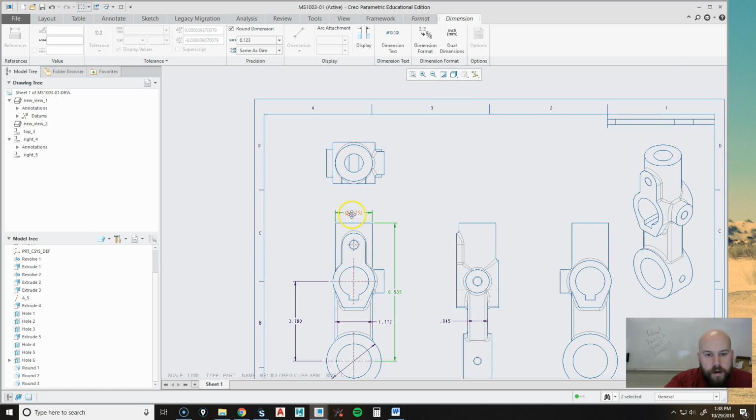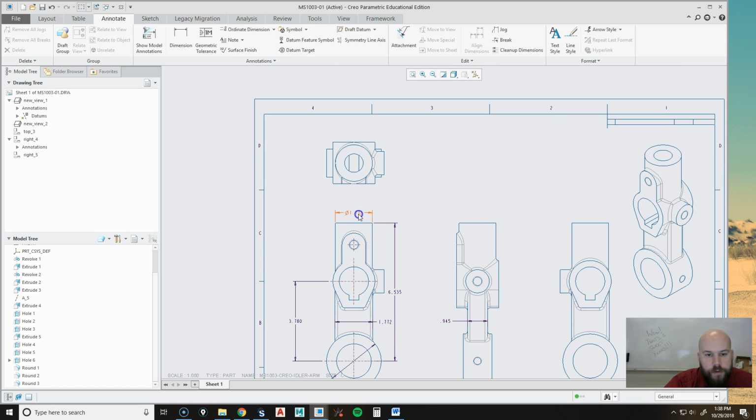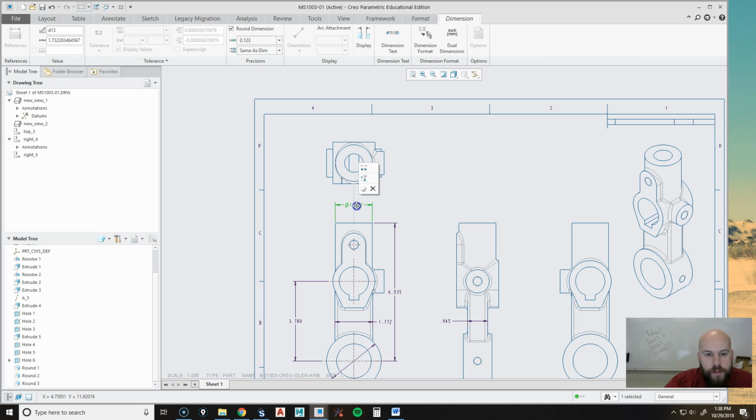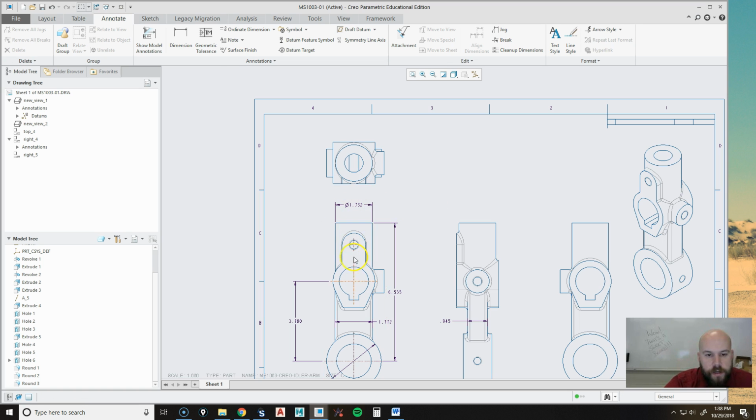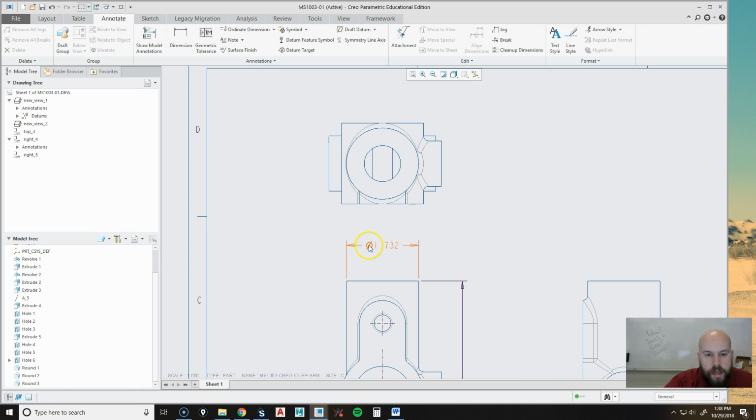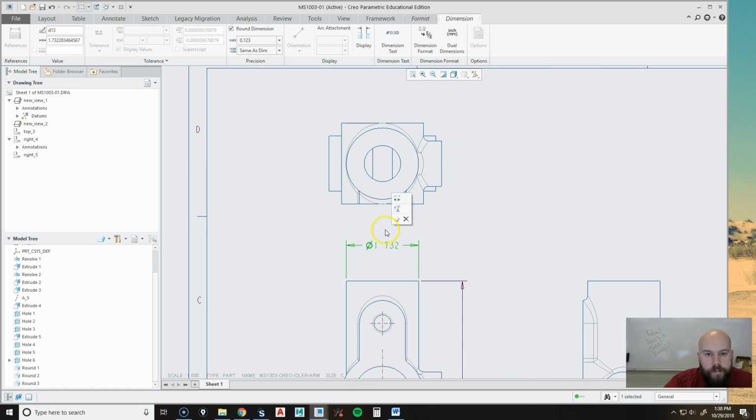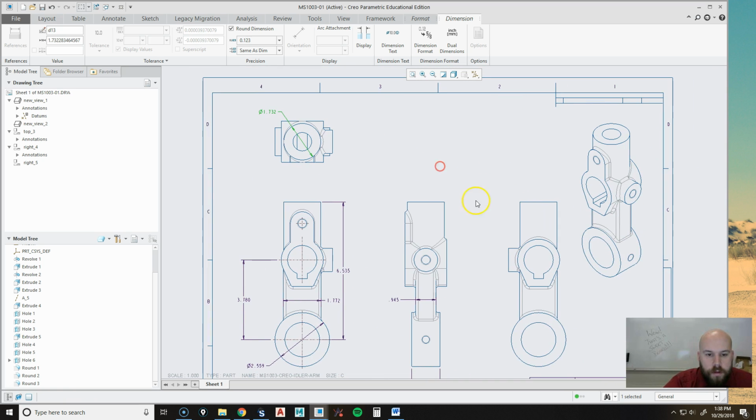This height here and this diameter could be shown a number of different ways. If I show it on this view, that means I need to show an axis down the middle to show that it's a round object. And my diameter isn't enough to show that. Because my top view is not going to have a whole lot of dimensions on it, I'm actually going to move it up there. I'm going to bring this around like so, or maybe I'll put it up. I'm going to have more room above the view, thinking long term here.